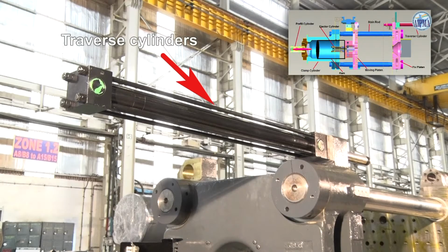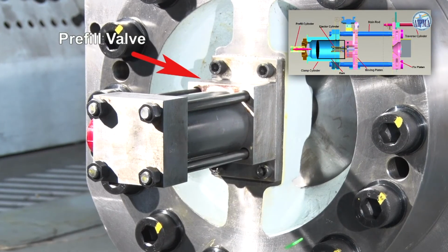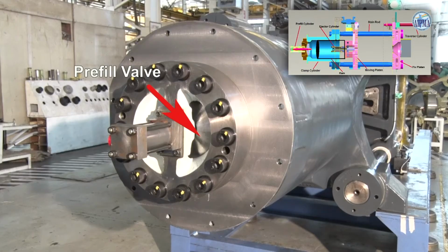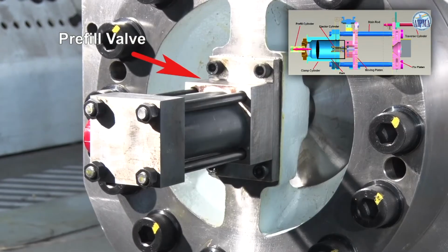Traverse cylinders. These cylinders are used for movement of moving platen. Closing and opening takes place by pull and push of the traverse cylinders. Pre-fill valve. Pre-fill valve is used for filling the oil from tank to clamp cylinder. Tonnage build activities after pre-fill valve is closed.